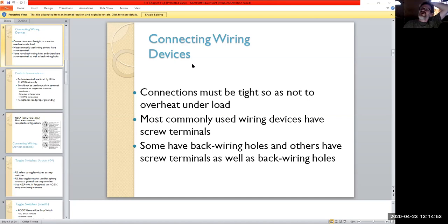If something's getting overloaded, even if the wiring is running really hot, you'd be able to see it on the infrared camera really easily. It actually highlights any hot points by comparing them to the temperatures around them. But an interesting thing: if you get an electrical connection that's not secured down really well at a screw post, say there's a little bit of an air gap between that screw and the wiring, where it's got a little bit of a wiggle to it, that will spark off an amazing amount of heat.